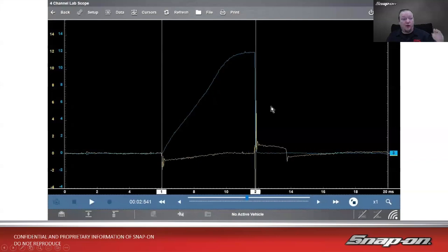Could see either or you could see a third option, which we're going to see in a little bit towards the end there. On the newer style coils, it does look nothing like that. So we can see dwell starts, current starts flowing in, firing line happens, the current drops off right away.